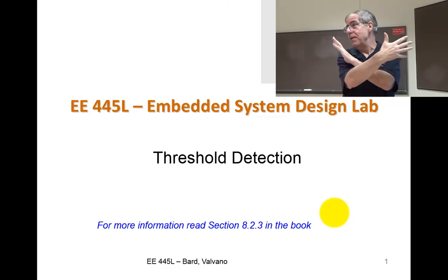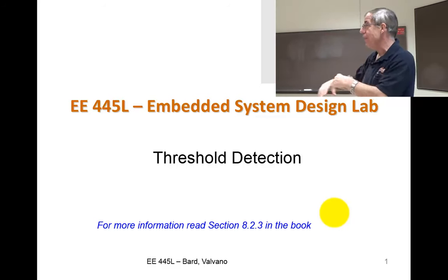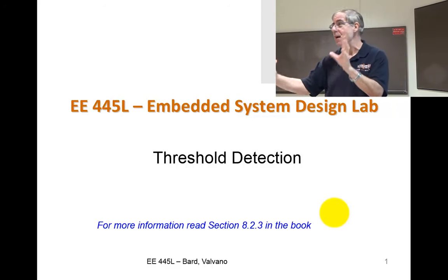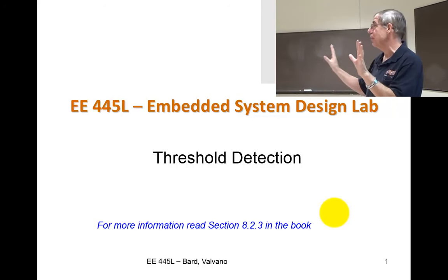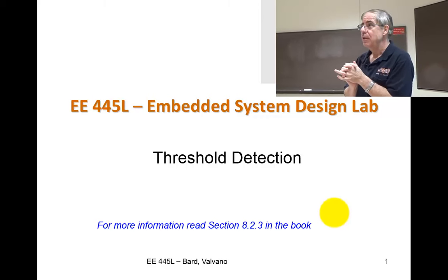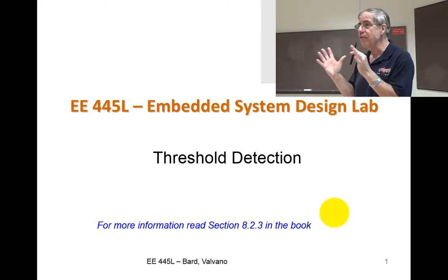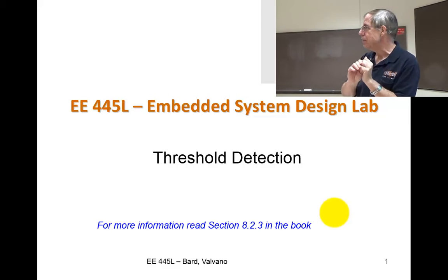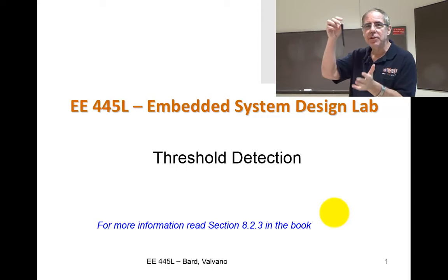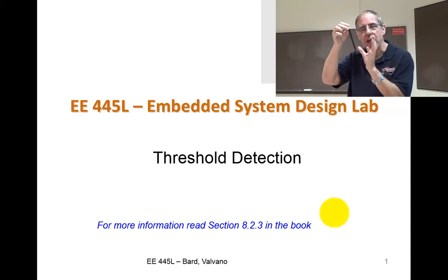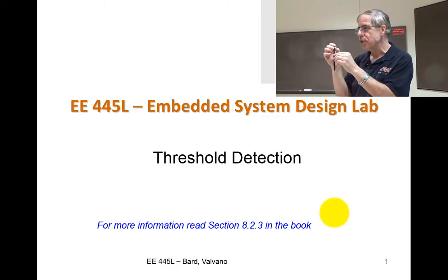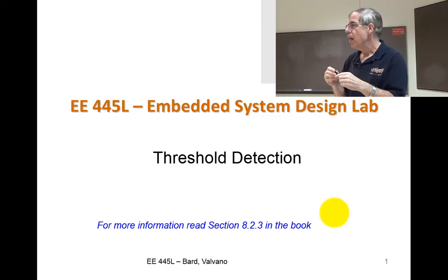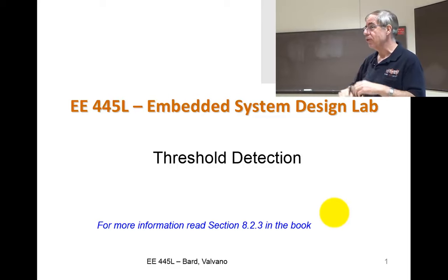But today we're going to talk about threshold detection, and we're going to violate the first rule of OpAmps. Remind me the first rule of OpAmps. Negative feedback, okay? This is positive feedback. Upside down, trying to balance the thing, it doesn't work because any small change makes it go unstable. And this was our negative feedback. Any small deviation from center caused the force to have it go more stable. But today we're going to use positive feedback for good, okay?